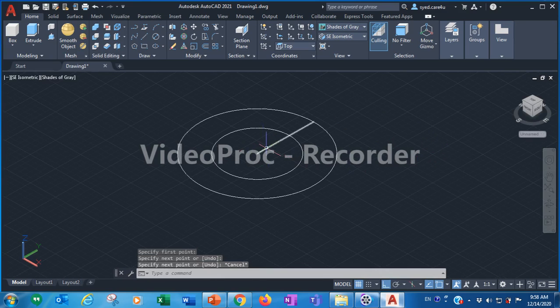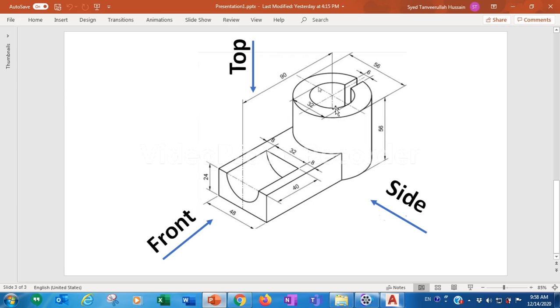If you consider this as the axis, from this axis towards the left side 3 and right side 3, this groove is present. The total width 6 is divided into two parts, towards left 3 mm, towards right side 3 mm. So I need to create two parallel lines. Towards left a parallel line at an offset distance of 3 mm, and right side also at an offset distance of 3 mm.